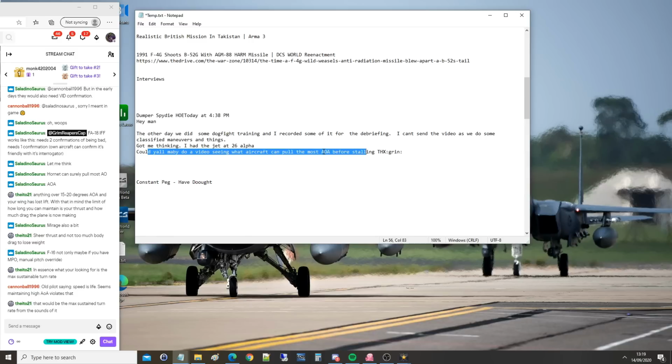So all else being the same, our imaginary fighters, one can sustain a maximum of 15 degrees angle of attack, and let's say you get another one that's a Hornet that could sustain 40 degrees angle of attack. I think the 40 degrees angle of attack will always have the advantage because it means that going around the circle of our knife fight, the guy with higher angle of attack can keep his nose pointed more at the bad guy than at the vector of the circle. It means his weapons employment is going to be easy, getting a lock's going to be easy and so on. Ignore helmet mounted sights and stuff, just basic kinematics of the fight.